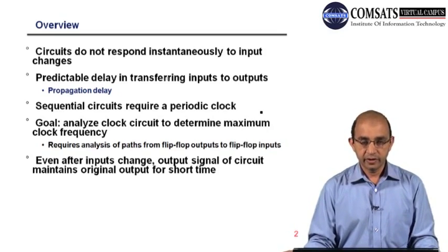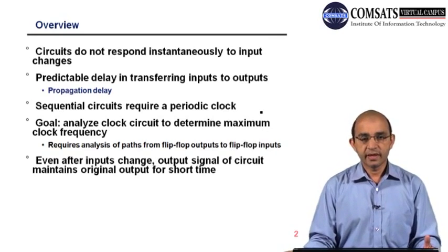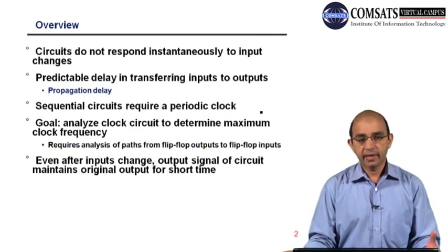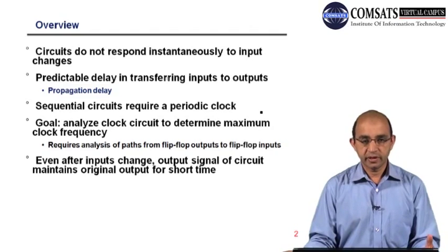We have to wait in order to see the effect of input at the output. So it means there is a delay while the input transfers to the output, and that delay we normally call propagation delay. This is regarding the combinational circuitry.